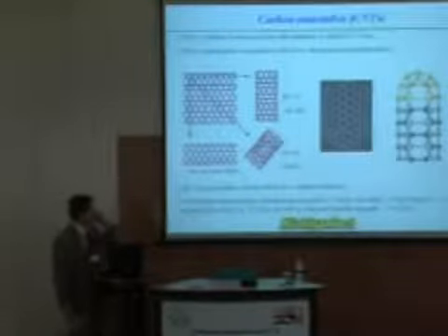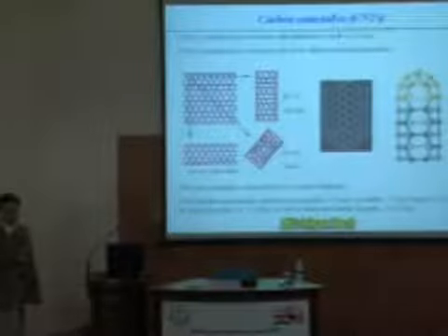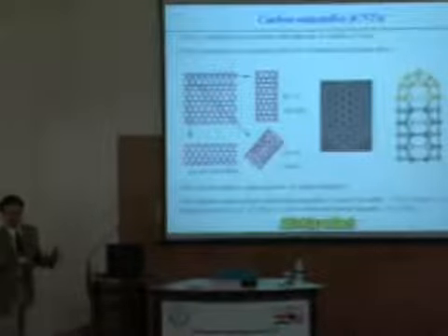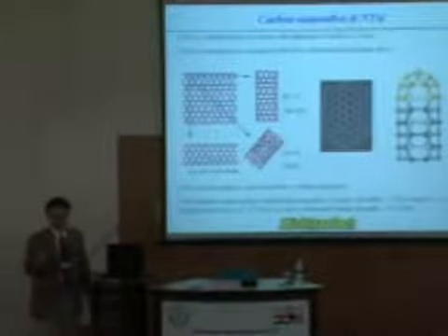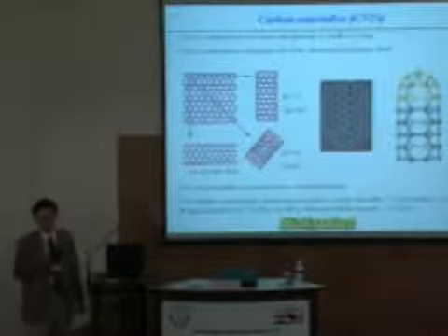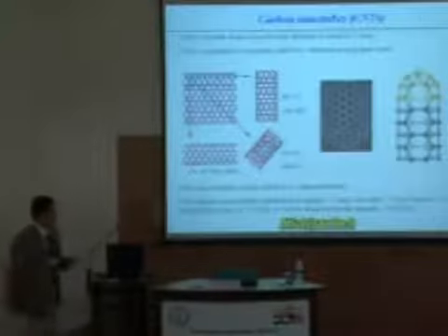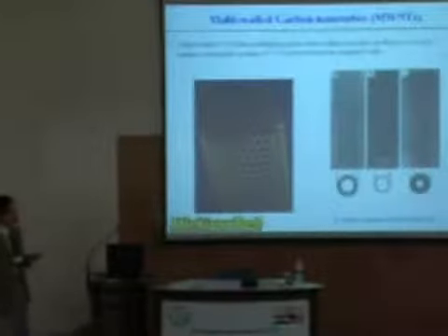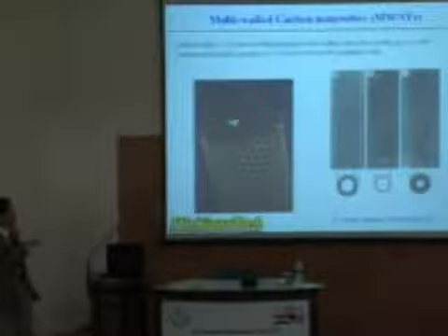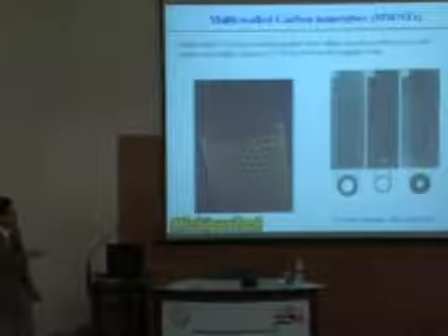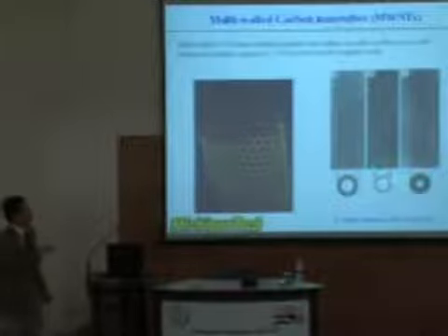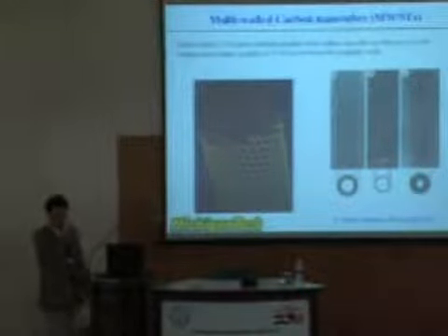The whole picture is to tell you that all the carbon nanotubes you make might behave very differently, and this is the main challenge of carbon nanotubes. If you have more than one shell of graphene, for instance 2 shells, we call it double-wall nanotubes, or if you have more, 5, 7, and so on, we call the whole class of materials multi-wall nanotubes.